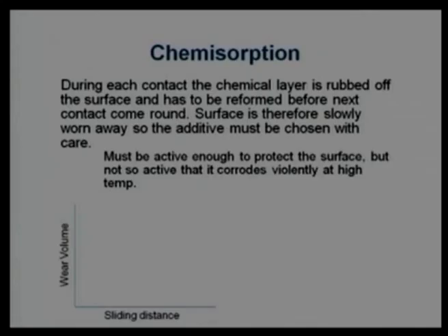Here we are not talking about wear rate, we are talking of the total wear from the scratch, how much wear has occurred. If I plot this, first, this line is clearly showing Archard's law. In dry condition, they are in proportion. Sliding distance and wear volume will have by and large a linear variation.